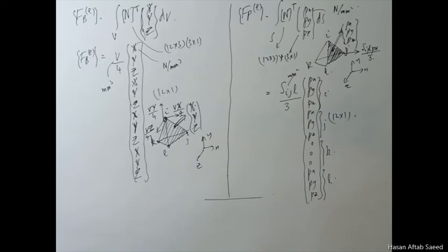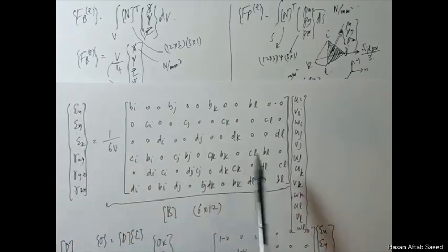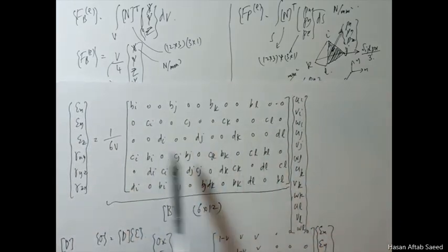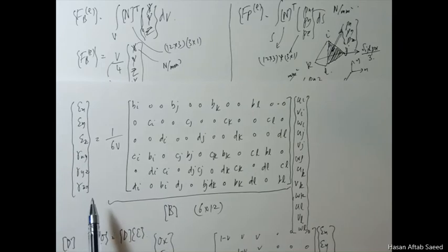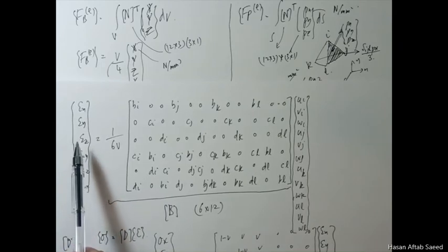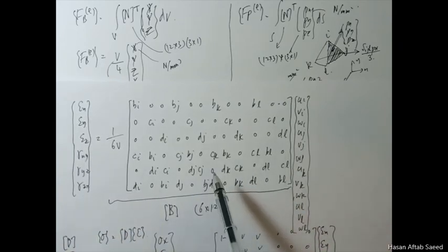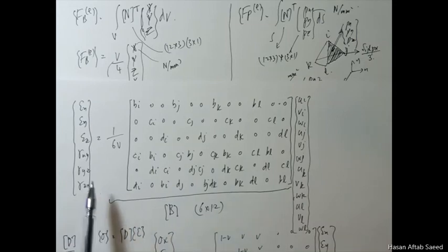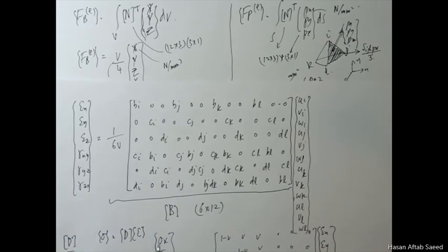Obviously after that, ultimately you get this using B, but these again are total strain vectors. This is a total strain vector because it includes the effects of thermal strains. Now if you use this expression as it is here, you'll get an overestimation of stresses.